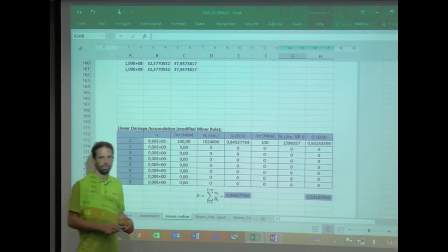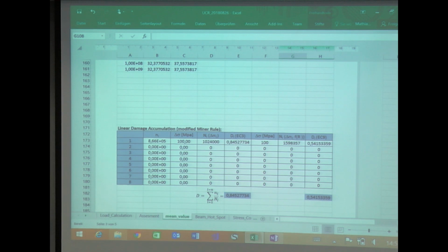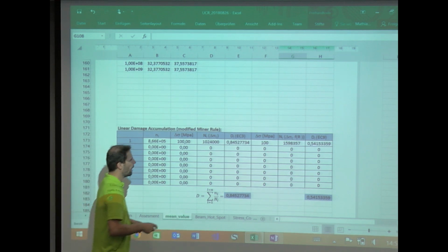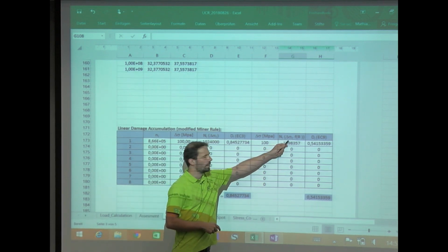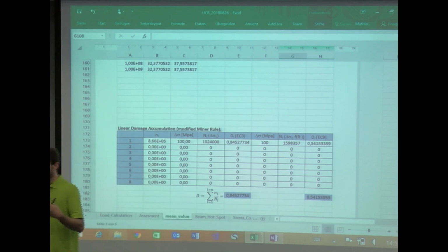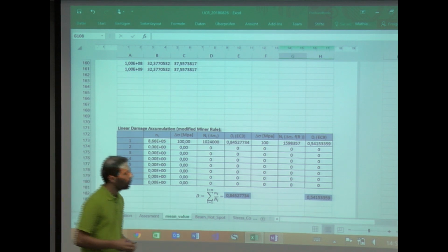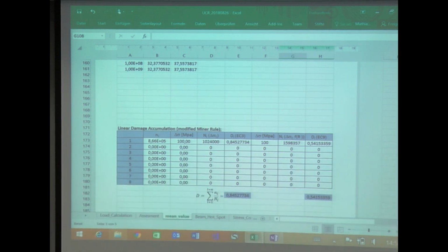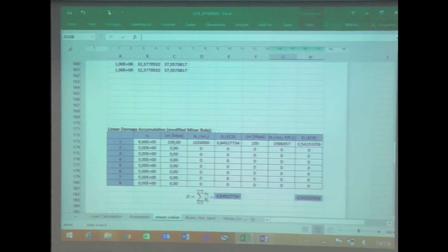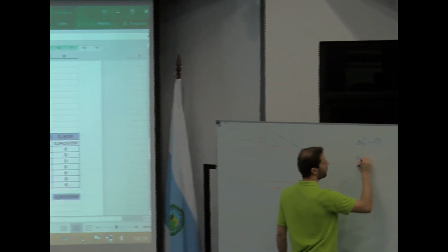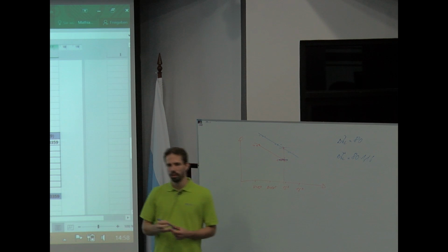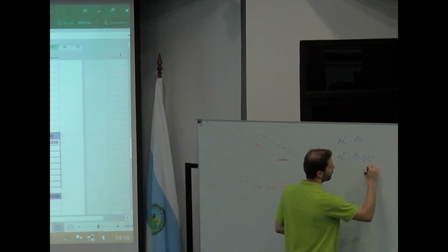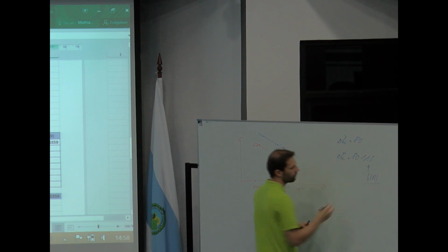So you have the same linear damage accumulation of 0.84. And on the other side, you have here an increasing of your SN curve. So the value of your delta sigma C, which we have chosen before as 80, now has a new value of 80 times 1.16. And this is our value FR.